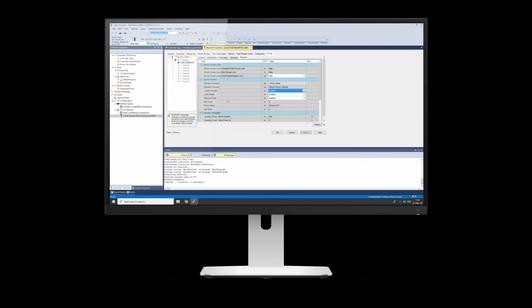So you can now change parameters live from your sensor directly through this window. In the next demo, I'll show you how we can do message instructions to these variables from your program directly. But if you do want to just set up something quickly in your sensor, such as a threshold, you could just come in here and do it directly. So you set point threshold, you could type in a value in there directly. Apply, that would then save it to the sensor, in the master itself, and as part of your project. And that's it, simple.